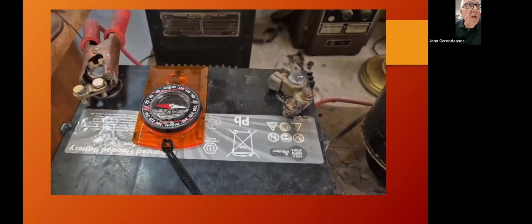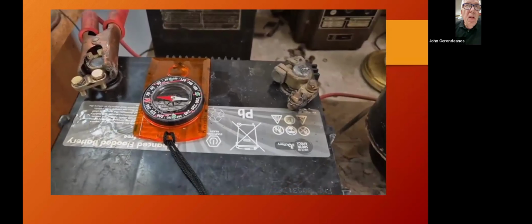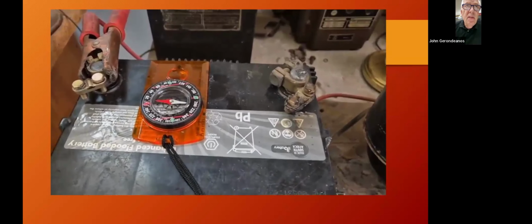there are 400 turns on each pole face. There are 4 layers of 50 turns, sorry, 200 turns on each pole face. There are 4 layers of 50 turns on each side, so that's 400 turns. And it's a huge soft iron lamination, and that thing will saturate pretty much anything you put on there.